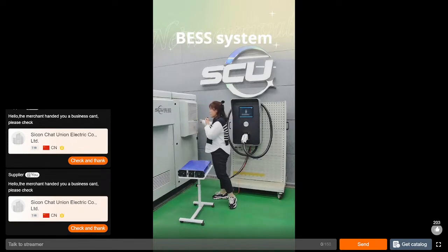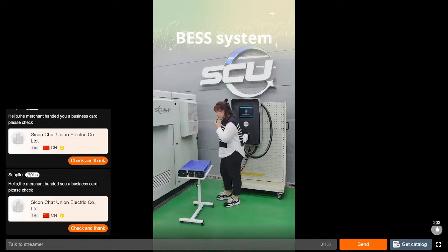This part is the air conditioner, and it will run automatically when the temperature increases to 30 degrees. The air conditioner will start cooling, and when the temperature decreases to under 15 degrees, the air conditioner heating will start. After the temperature increases to 20 degrees, the air conditioner will stop working.